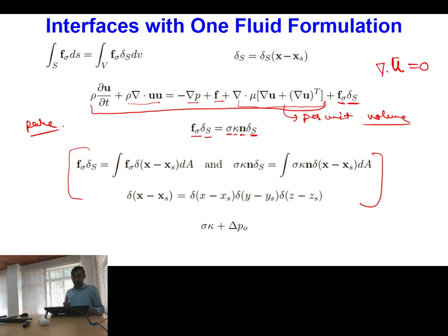Now in this system, one more important point you can see, that if you have to assume the gradient of the surface tension, then by doing the exact computation, at what part of the interface, what is the value of surface tension, despite that, you can simply also introduce this by adding some additional term, because the presence of the contaminants is only modifying the force. So that force you can directly substitute as some additional constant along with the surface tension to account for that.